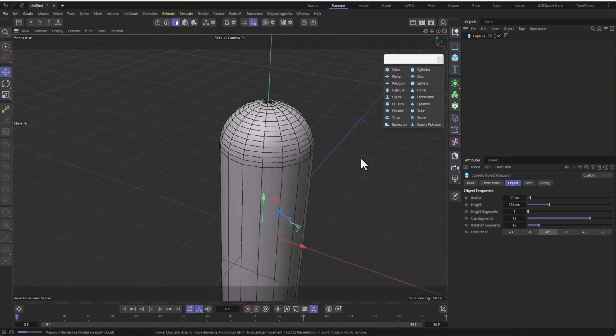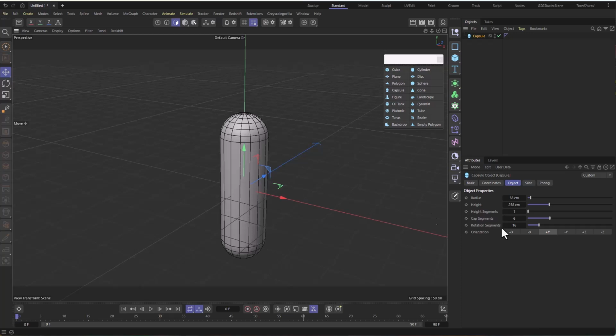This is very similar to adding more subdivisions to your fillet. If you want a smooth rounding, then you should have more subdivisions so that in the 38 centimeters that I am making this edge go to this edge, there are enough polygons to smoothly connect them. The last thing that you have is your rotation segments. So that is how many segments are going vertically to make this a rounded object. So if I increase it, it gets rounder, and if I decrease it, it gets less round.